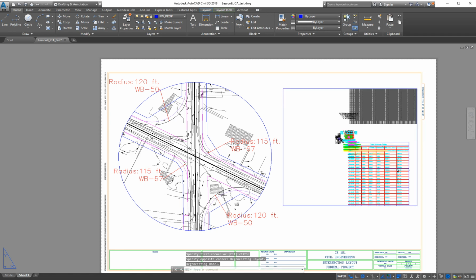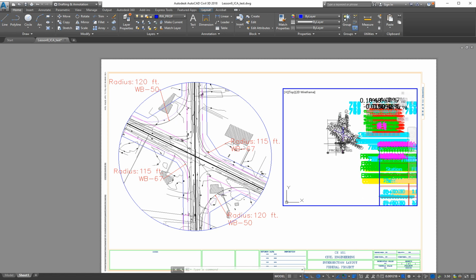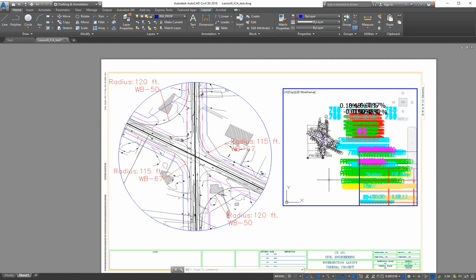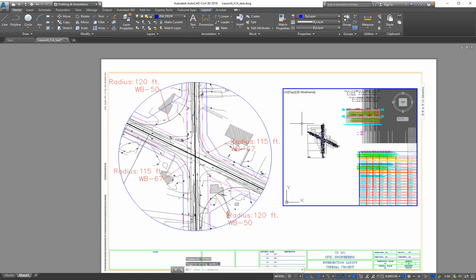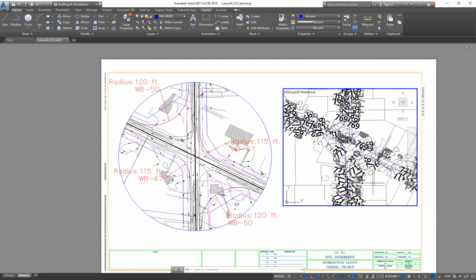When it comes up, it automatically puts you in there. So I'm going to double click in there, and that looks like crap, right? This is zoomed out so far. These are elements that are in there that you don't normally see. Our drawing is actually right in here, and this is where this regen command is going to become super helpful. If I zoom in, it still looks like a dog's breakfast, I guess they would say. If I type in regen, it'll get a little bit better. Okay, and I can see this is starting to be that intersection over here. Actually, when I hover over stuff, it highlights it in the other viewport too. Then this text is all associative sized, and so to reassociate it, we've got to do regen again.